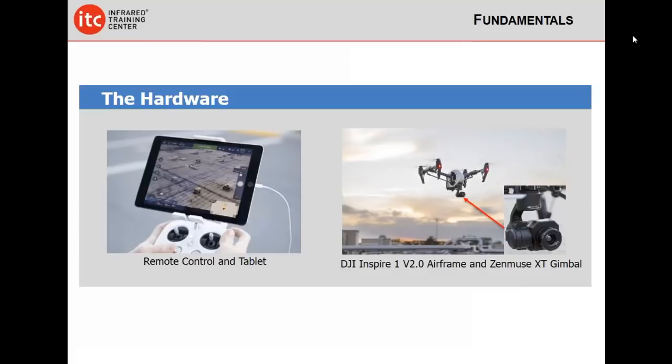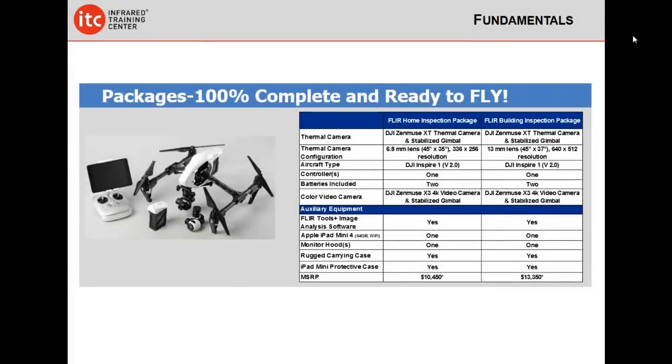Hardware. Of course, we have the different types of hardware. We have the DJI controllers. There's other controllers out there that perform differently. And we also have different types of software out there. The DJI Go software and the XT software now allows us a lot of interaction. We can actually do things like nuke the camera. And if you haven't heard of nuking, nuking is very important because it refreshes the pixels on your camera. We discuss this a lot in the level 1 SUAS course and show you how to do that in this course as well. So nuking is very important, non-uniform correction.